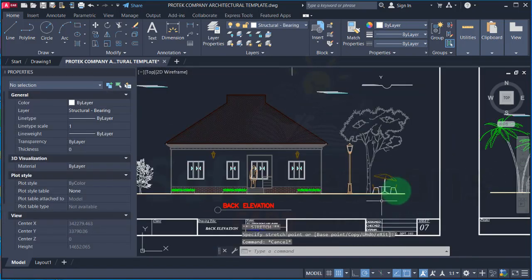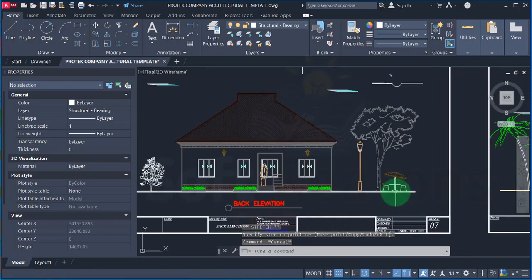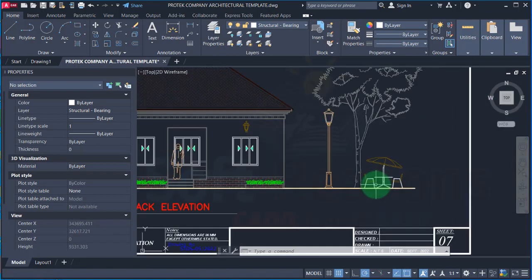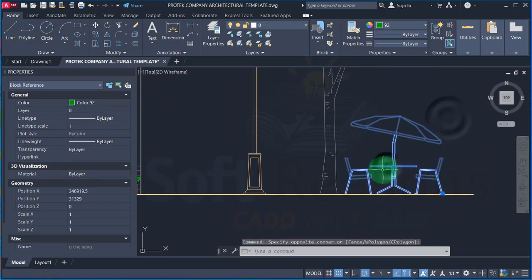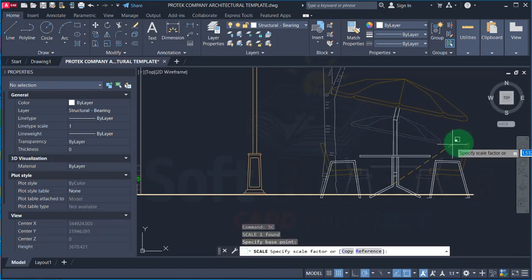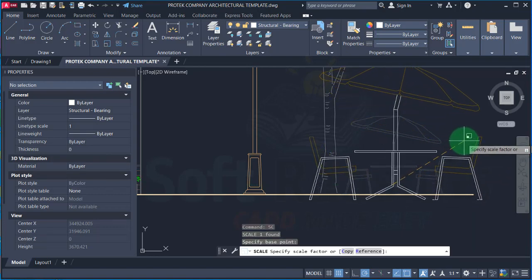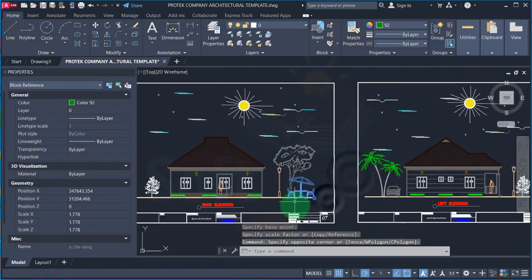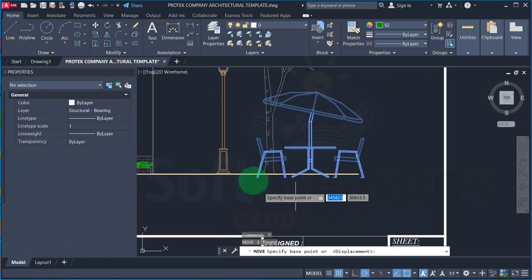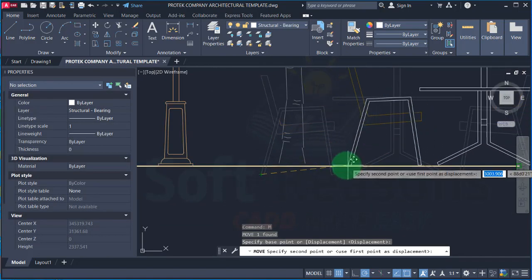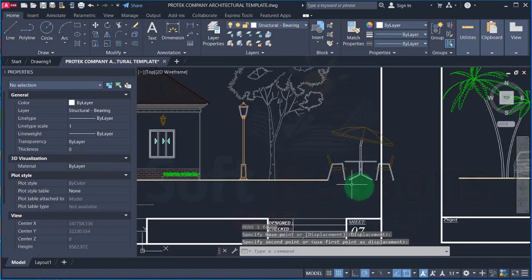Okay, so you can see the way it now looks. If this is not visible enough for you and you want to scale it so that it will be bigger, you can highlight it, type SC on the keyboard, enter, and then select it and move your hand this way. You can see it's becoming bigger just like this. If this is okay by you, you just click like that, select it and then adjust it again by using M for move on the keyboard, pick the base point and then move it to this other provision.